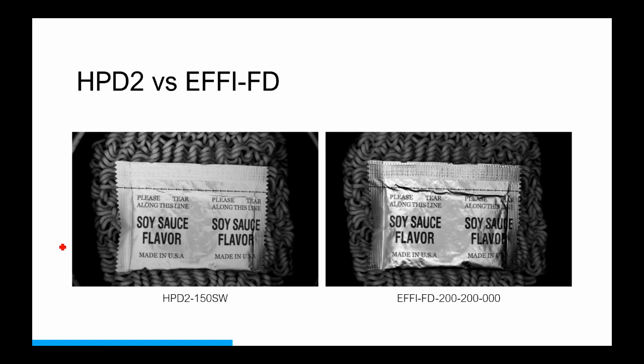And then next from there is the LFX-V, where the light shines into a light guiding plate that has little dots that direct the light down. Also very diffuse. Both of these lights typically need to have, especially the LFX-V, a shorter working distance for the most diffuse results. And then an FE flat dome light is essentially a backlight with a camera hole in the middle for the camera to look through.